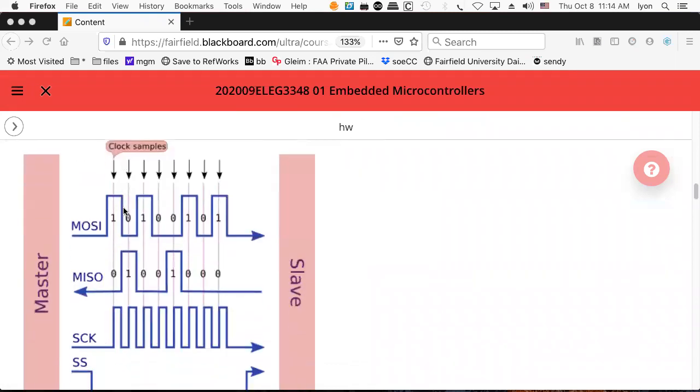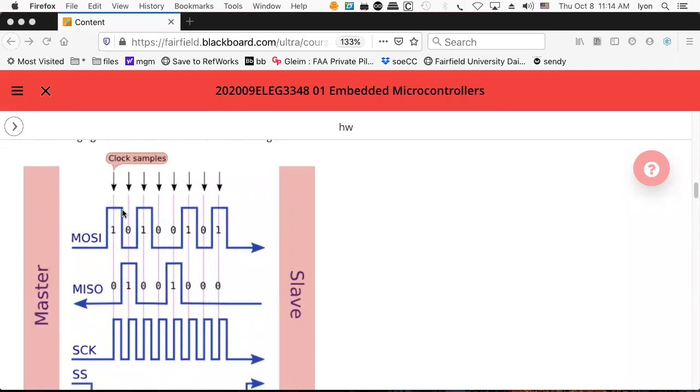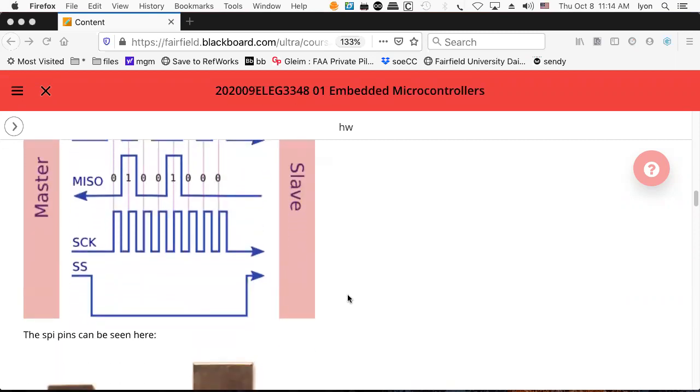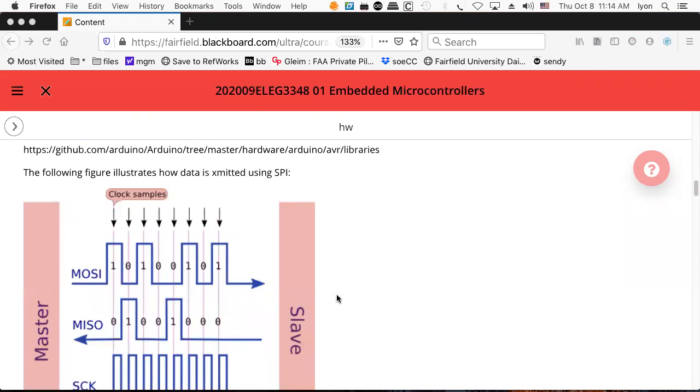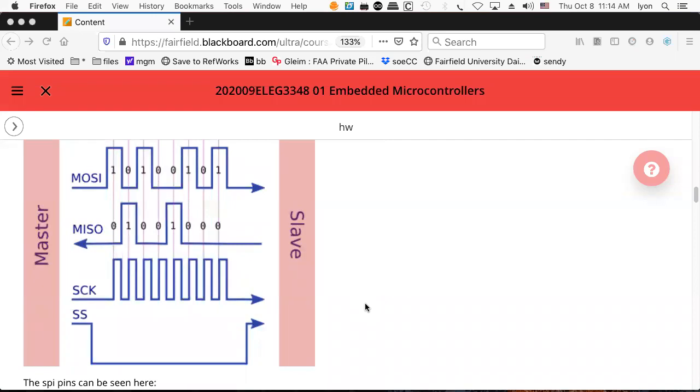And so, one thing you can say about the SPI is it's extraordinarily fast. It's full duplex. The serial clock for the actual SPI interface has a minimum of divide by 2 in the prescaler. So for our little 16 megahertz Arduino Unos, it'll probably be running at about 8 megahertz, which is about as fast as that Arduino is going to be able to take any data anyways. But if you had a faster computer, SPI will run faster. And if you have a 64 megahertz clock in your little CPU, this thing will probably run at 32 megahertz.